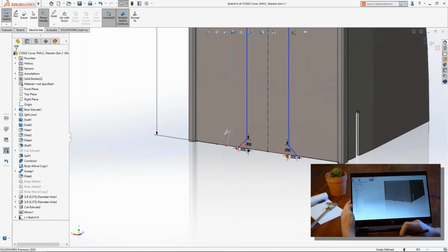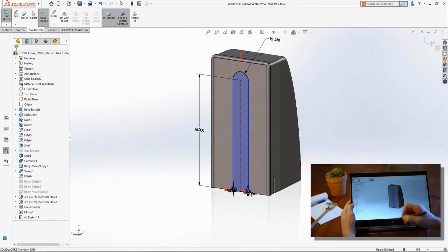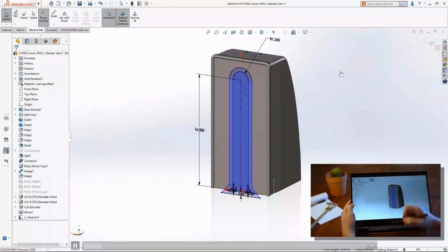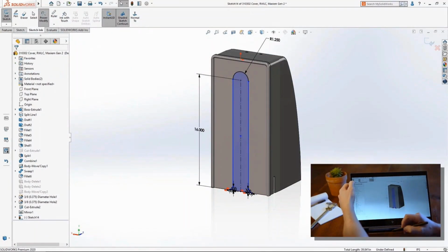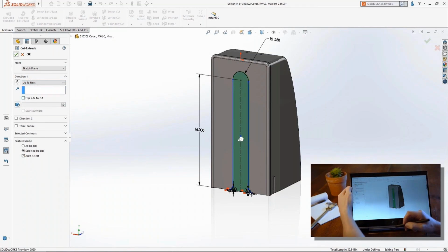If we do an X, it's going to actually split entities. We can extend lines like you see there just by drawing an extension of our lines. And if we want to delete anything, we can just start with a squiggle and then sketch it out through our line. If we do a double stroke through an entity, it's going to offset it. And what you just saw there is a double parallel stroke that actually offset all of our contour when we complete that double stroke within the contour itself.